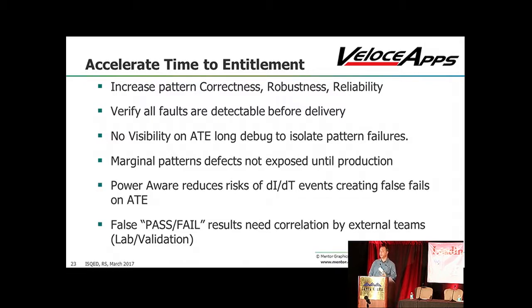Also, you can do power aware. So what power aware allows you to do is look at various aspects of your design and say, well, while I'm scanning this stuff in, I'm causing this di/dt event. You want to know that in advance, and that'll allow you to change the way you structure your pattern.